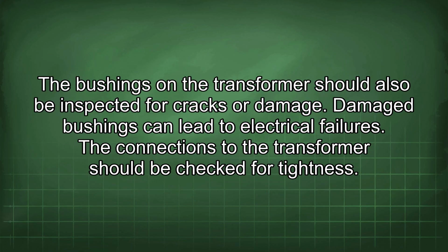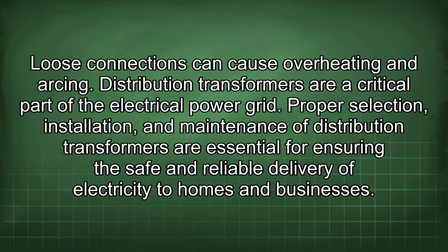The bushings in the transformer should also be inspected for cracks or damage. Damaged bushings can lead to electrical failures. The connections to the transformer should be checked for tightness. Loose connections can cause overheating and arcing.